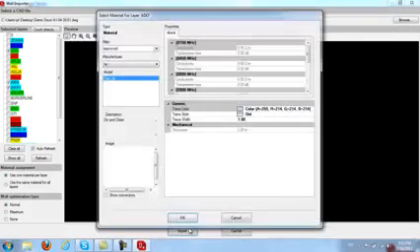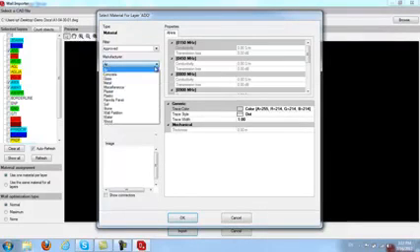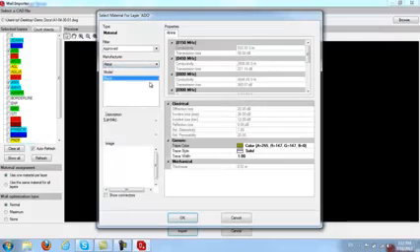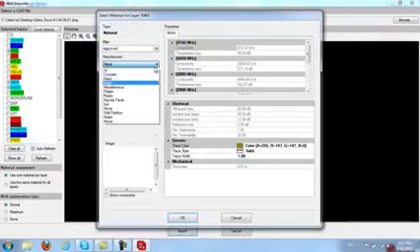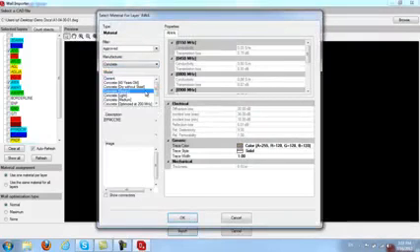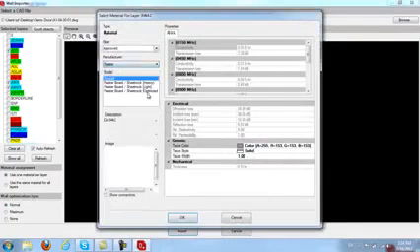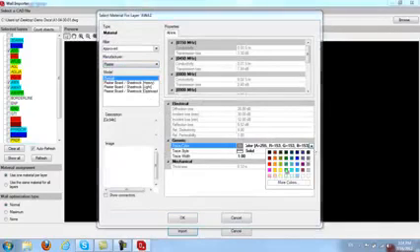Once we click import, the software will ask us to specify different materials for each layer. So for my doors, I will select metal, and notice here you have all the transmission losses and so on for the metal, and those will be taken into consideration when running your maps. And notice here it gives it this metal color, so I will click OK. For my next layer, my outside walls, I'm going to select concrete, heavy, and for my inside walls I can do plaster, drywall. Notice that you can always change your color directly here, so you can pick any wall color you want.